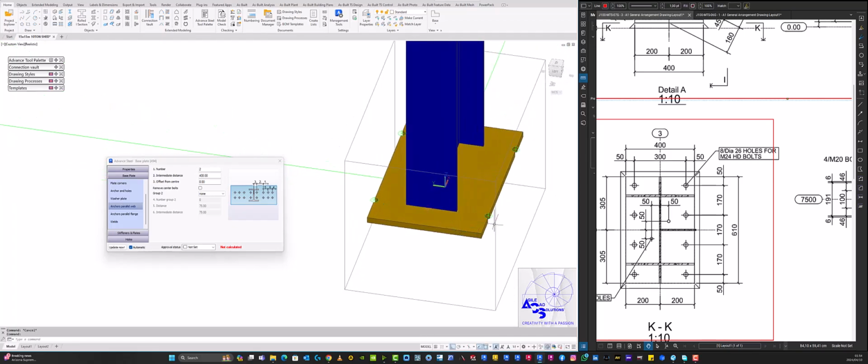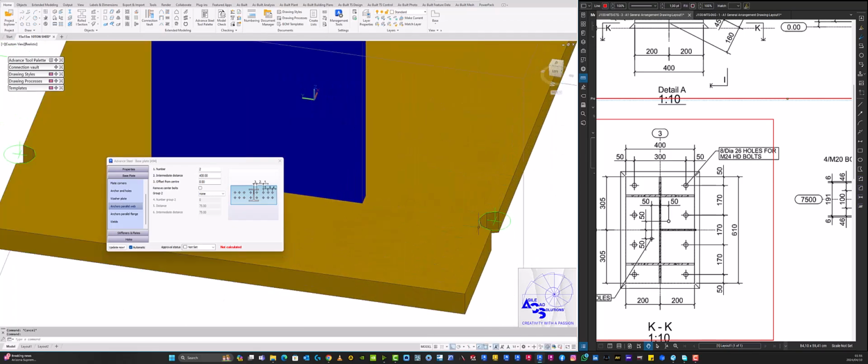As you can see, the center is running along the edge of the plate, and that edge is where we've got our 400. So we've got 2 of these, which are the holes on the drawings, and our intermediate distance there is 300, not 400. Right, that's more like it. And there is no offset from the center, so we don't need any offset from the center.